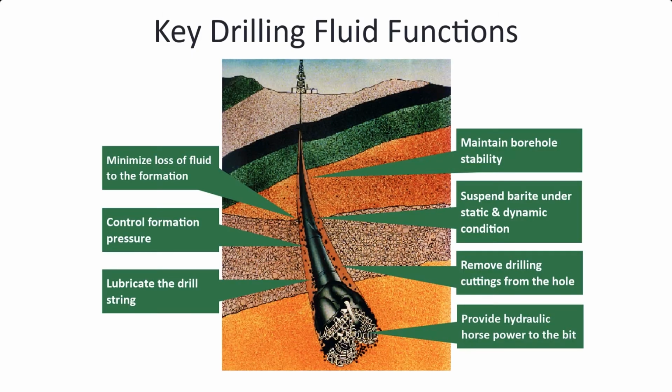retort test. Some of the most important functions of the drilling fluid are to control formation pressure and to maintain the borehole stability. Controlling formation pressure while drilling into the wellbore is accomplished by adjusting the specific gravity of the drilling fluid so the pressure gradient of the drilling fluid within the wellbore exceeds the pressure gradient of the fluid in the formation.